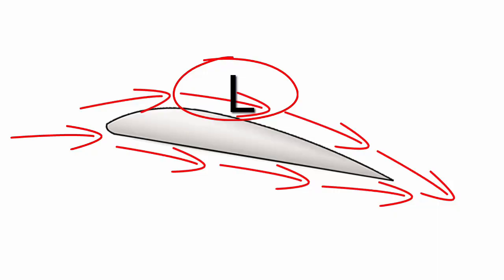However, the pressure difference between the upper and lower surface of the wing alone does not account for the total lift force produced. The downward and backward flow of air from the top surface of a wing creates a downwash. This downwash meets the flow from the bottom of the wing at the trailing edge. Applying Newton's third law, the reaction of this downward-backward flow results in an upward-forward force on the wing. Lift is also generated by pressure conditions underneath the airfoil.